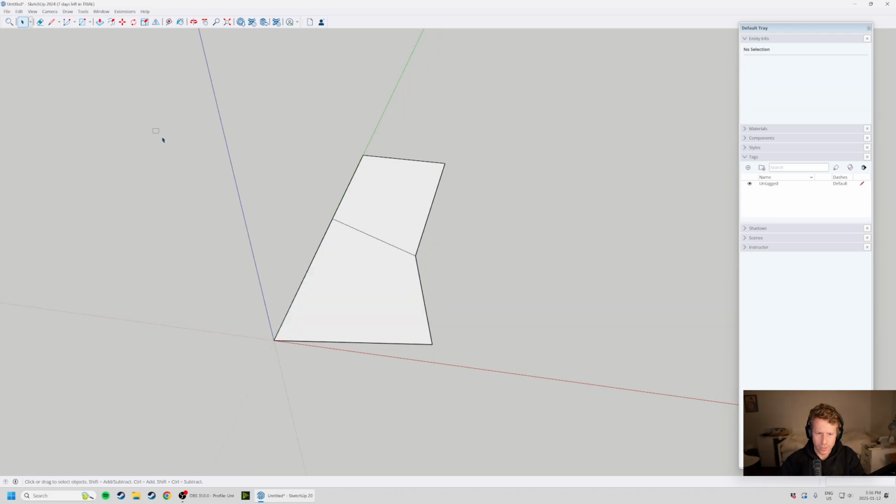Conversely, if I just select using the window, I'll just get the bottom and this top piece here. If I use the bottom right to top left, anything that hits that edge, it will select for me. You should try that out. Super helpful when we're doing small buildings, big buildings, all that fun stuff.